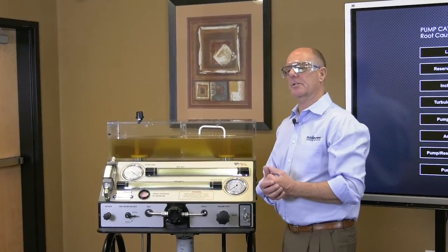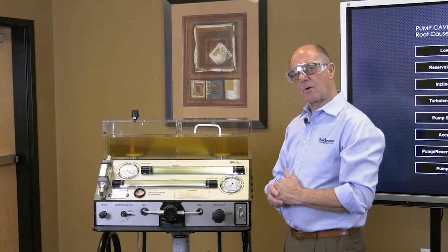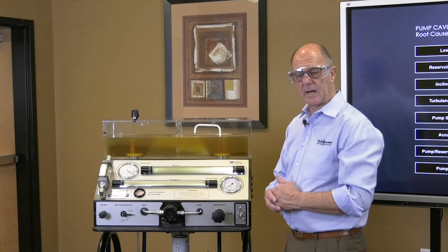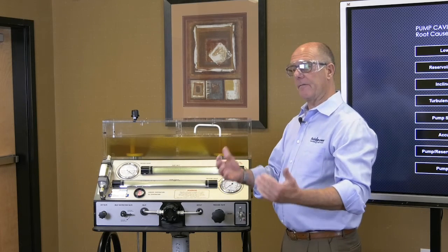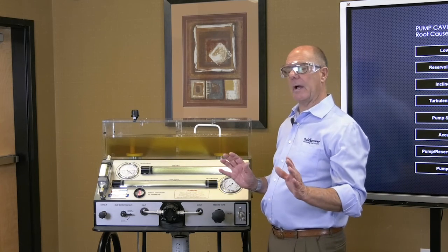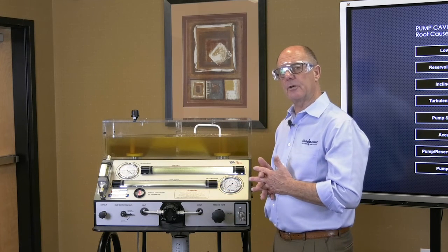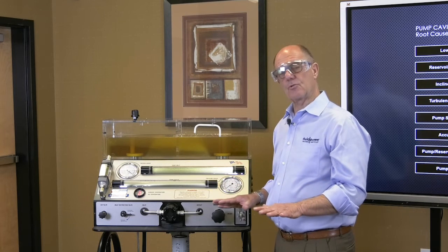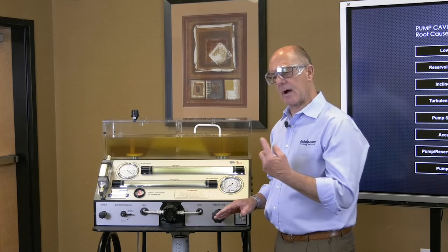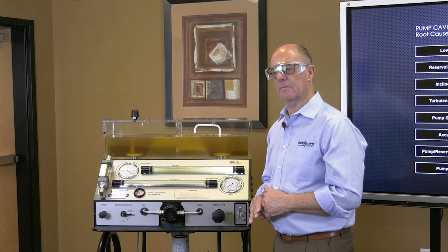If I've designed a hydraulic system whereby I haven't taken into consideration the volume displaced by large bore hydraulic cylinders, number one, and number two, the volume occupied by hydraulic or hydropneumatic accumulators, I could, by virtue of design or oversight, have a problem with cavitation. When I extend cylinder rods, or I've stored energy in my accumulators, my oil levels have dropped to a point where we're encroaching on the intake, and we are now vortexing air into the intake of the pump. That's another consideration in terms of design.